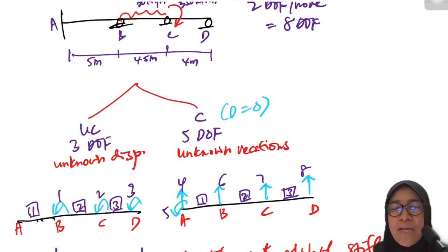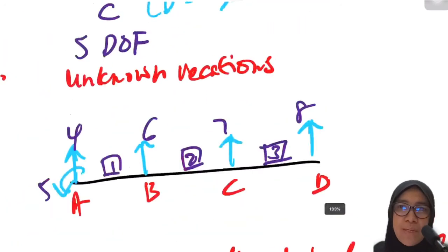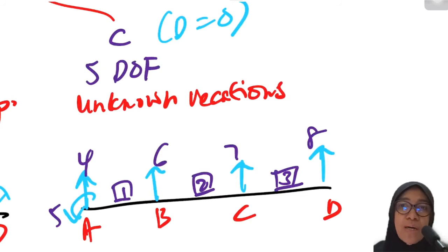if we use the word displacement, it can represent the rotation as well as the vertical displacement. If we use the word support settlement, it means that it is settled downward, means it is in the vertical direction. And support settlement always occur in constraint, because support is in constraint system. So settlement must be put in constraint system. So by looking at the constraint system, there are four Y values: 4, 6, 7, 8.